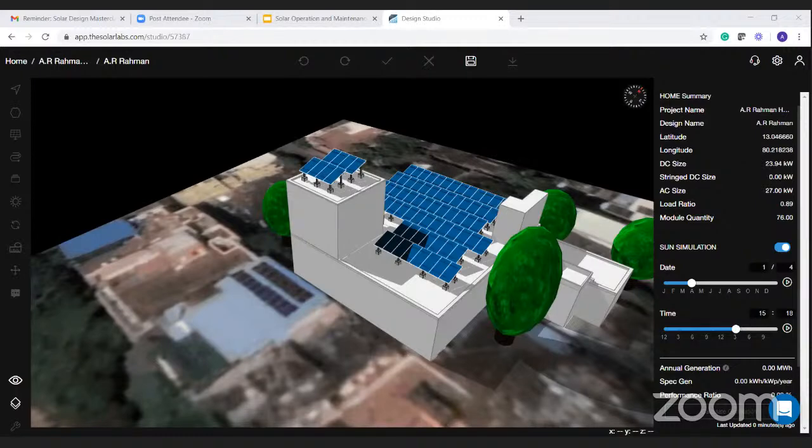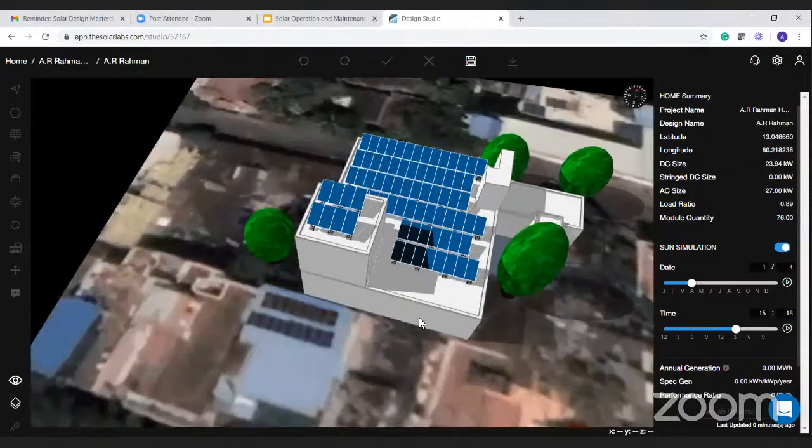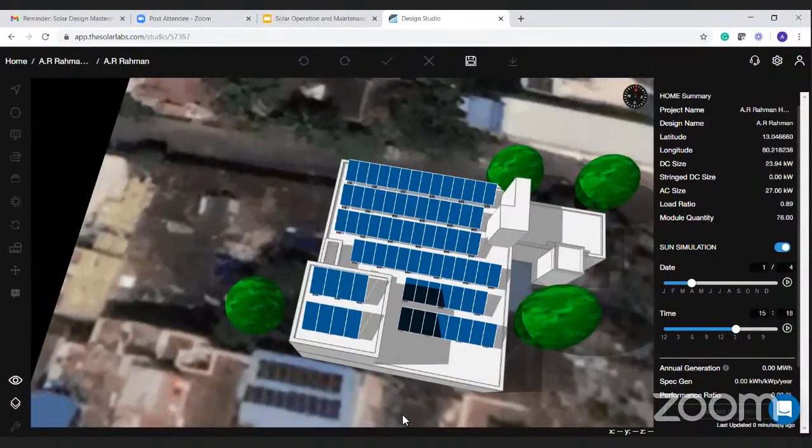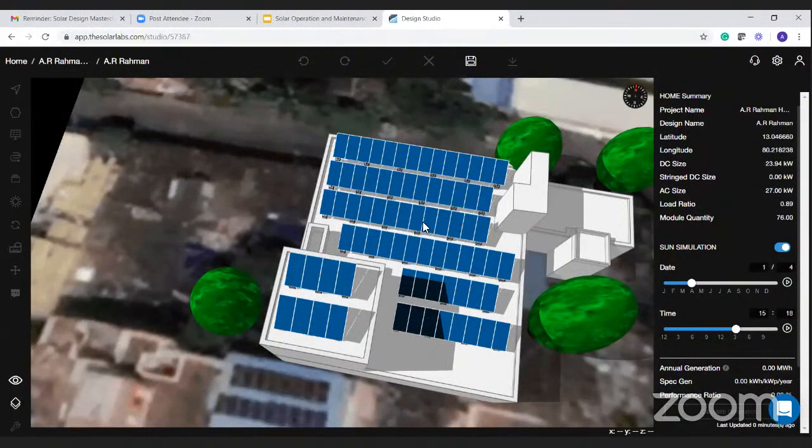So there's a question from Lalit Rawat. In this project, is a bypass diode installed per string or per module, to reduce shading losses? As of now, this software doesn't provide string-level detail. So in here we haven't installed a bypass diode, but yes, it can happen. Usually a per-string bypass diode should be installed. That will be more economical and feasible. So per string, I think, would be preferred in my view.